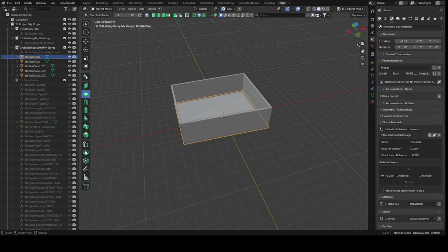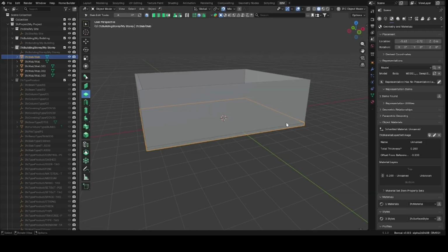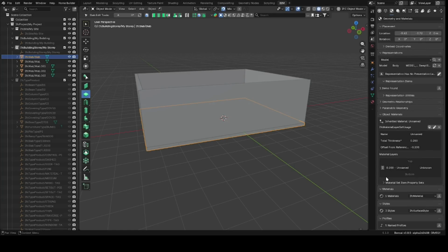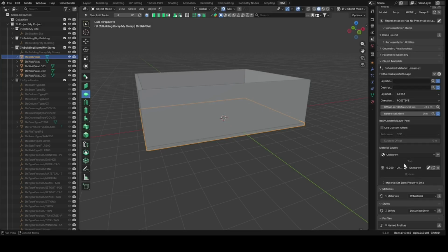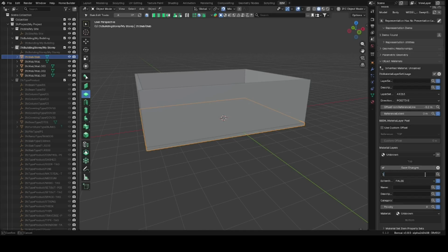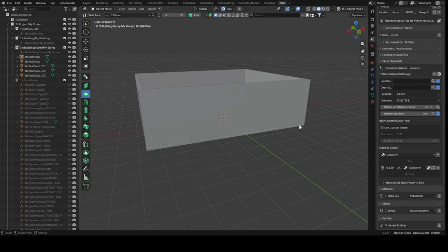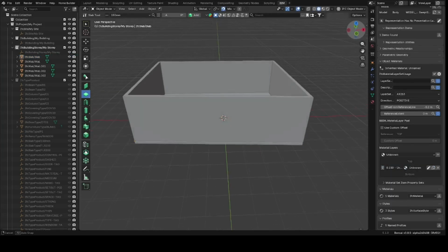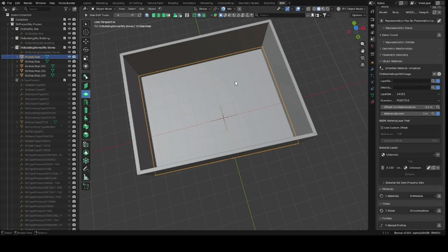But now when you look at your slab, it's already 200 millimeters, and to confirm that, at the object materials here you have 0.2 meters. So we can come to the same section we did for 200, set the thickness to 150 millimeters, and save the changes, and it has automatically updated itself. So I guess that's okay for now about the slab. You can create as many slab types as you want with different thickness.